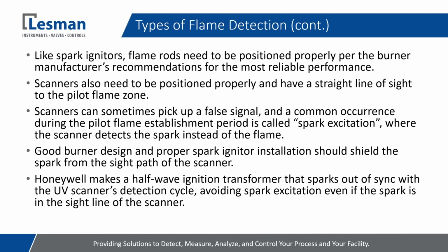And again, just like spark igniters, some of the issues that we see with flame rods is that they just need to be positioned properly, right? If you have it inserted not far enough or too far in, that portion of the flame rod that's exposed to the flame may not be getting the optimal current flow through the flame. So we just need to make sure that those are positioned properly, just like our spark igniters.